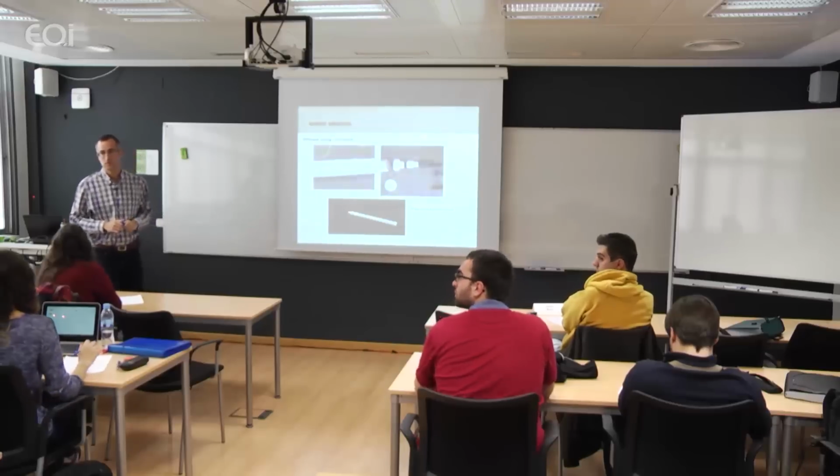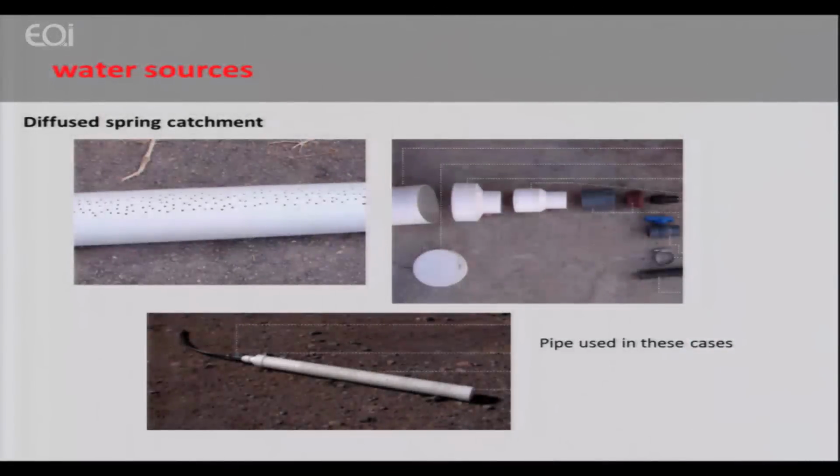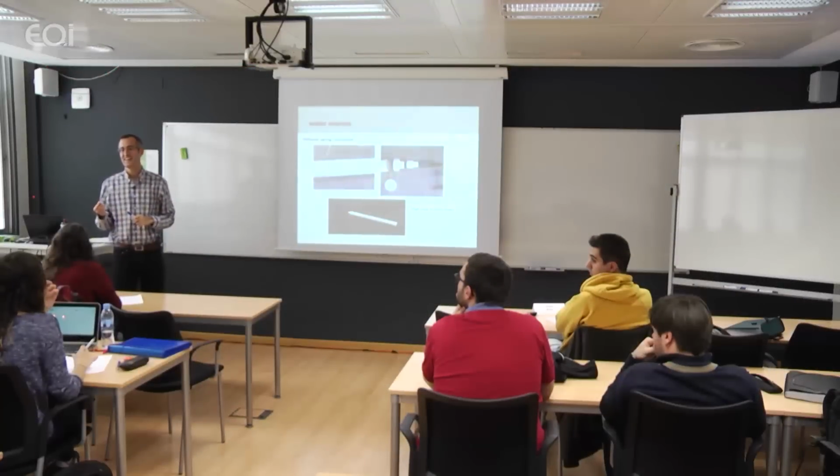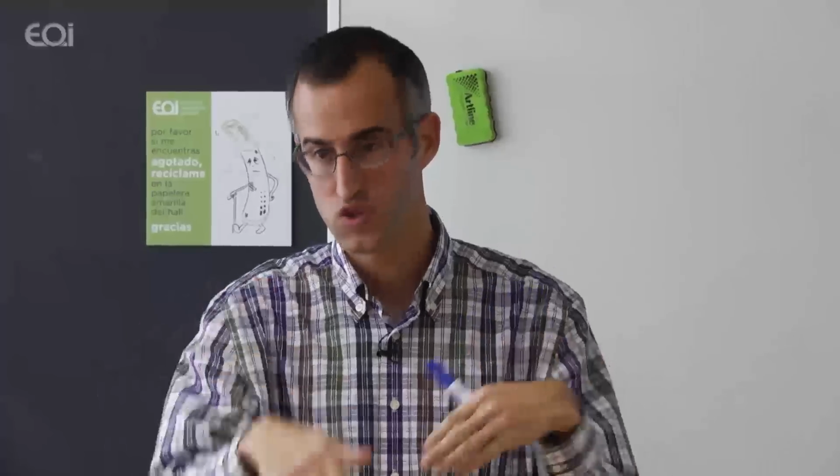Tell me, Edward. Are the holes always that small? Or can that depend? It depends. Here, you're going to install it in a ditch, right? So it's important not to install it with, for example, sand, because if the sand is very small, it will come into the holes. So depending on the material that you're going to use in the ditch, you can't make the holes very big. If you're going to use, for example, gravel, the hole has to be smaller than the material. But if you make very big holes, it's going to be good because the water is going to go very fast. So depending on the material that you use, the hole has to be one size or the other, right?